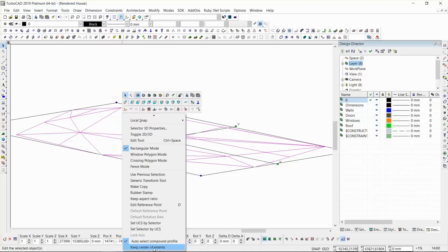Yeah, and remember everything is scale 1 to 1, so you can measure that profile anyway. It's the same as we do, say, roads or railway lines. You first take the level, and then you work on a 0 level, and you look at your cut and fill. Yeah. Yeah, so now you can definitely do that.